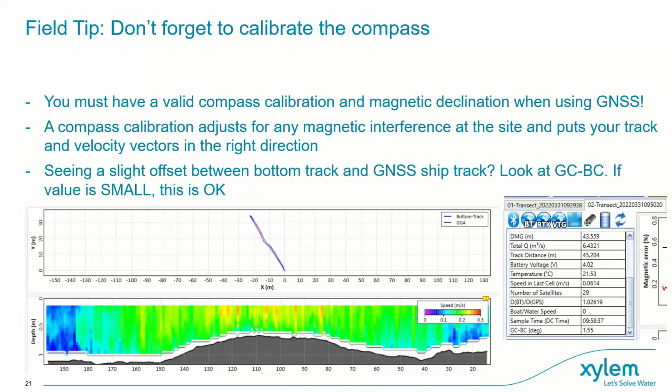And so with that, a field tip: don't forget to calibrate your compass. You must have a valid compass calibration and magnetic declination when using GNSS, also known as GPS.